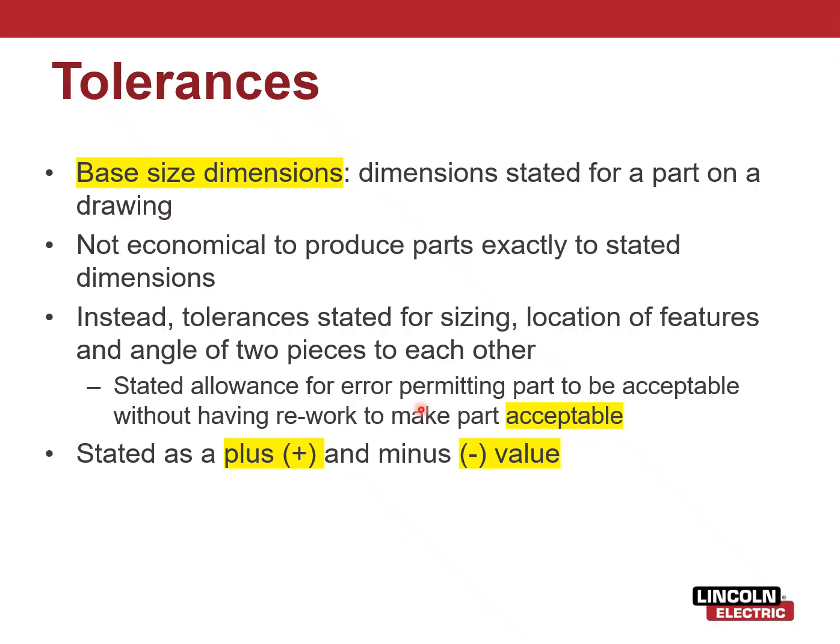All right, and for the fabrication guys, I'm sure you'll hear Camacho talk about tolerances on and off when you're doing some of your 3A projects. We always have a plus or minus tolerance on projects, right? If you're squaring up a trailer, you want plus or minus a 16th. Okay, so that's no more than an 1/8 inch off total. And so on prints, these are going to be denoted as a plus or a minus.